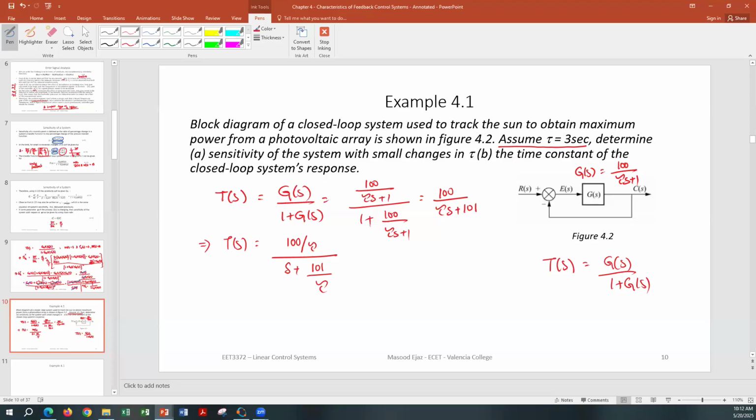But if s is equal to -2, then 1 over 2 is 0.5, so -t over 0.5 takes half a second. So the closer the s value is to the origin, the larger the time constant, because the time constant is 1 over that value.